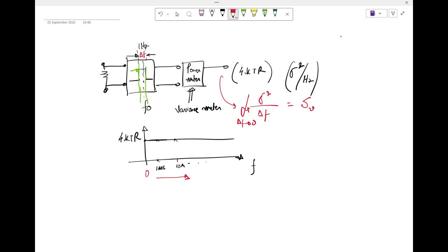So similarly, when you take any signal, or rather in this case noise, when you are talking about noise, you are talking about essentially how much power you have within a certain bandwidth, right? Now when you are talking about noise and you have to take into account mathematical consequences, you have to take into account negative frequency also. Does it mean that we end up with 4 kTr in the negative side also? What do you think? What does your gut tell you?